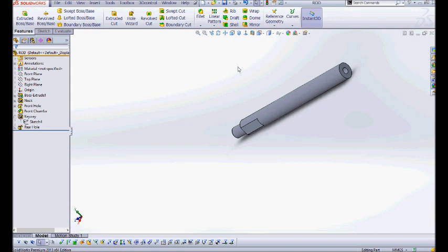Okay, so I'm going to click on Edit Sketch Plane, and notice it highlights the face. It shows me the face where the sketch lives. And I don't want that face. I want this face, right? So I'm going to right-click and say delete, and then I'm going to select that face, right? And then I'm going to go green check.